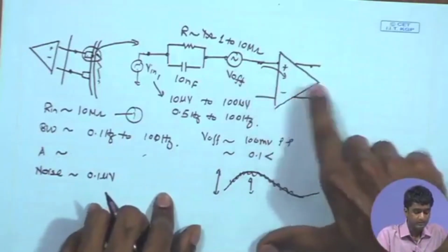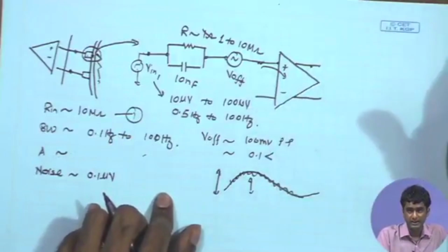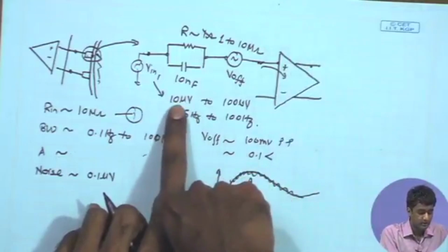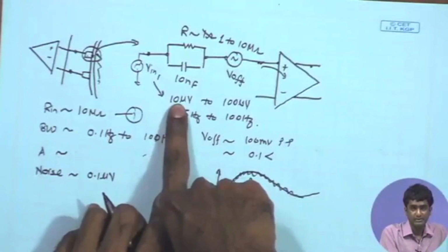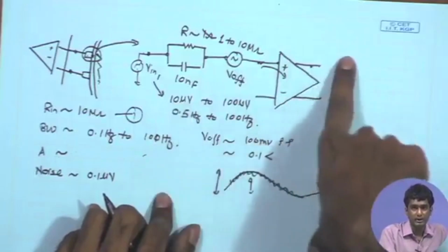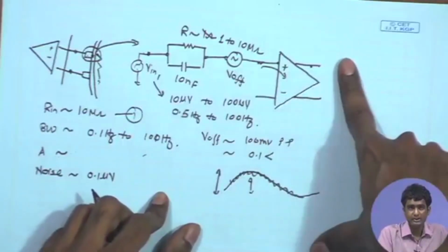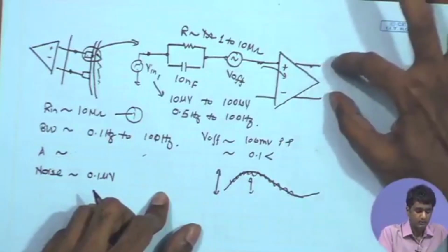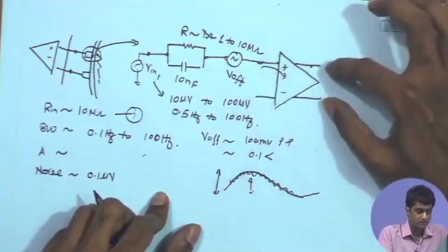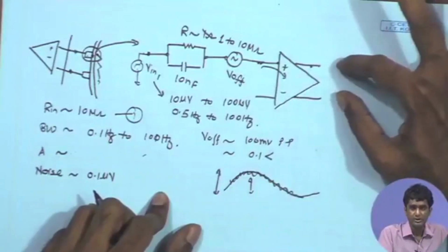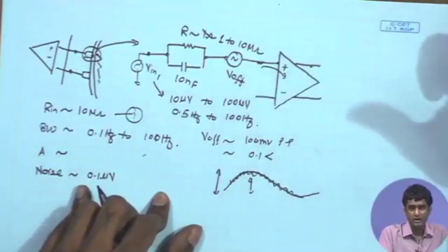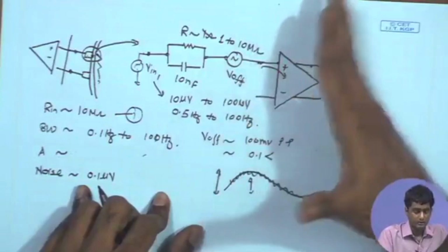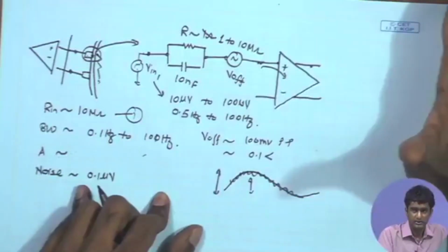So, that means the maximum gain that you can have for the amplifier will be just 10, and even after amplification the desired signal is getting amplified only by a factor of 10. So, from 10 microvolt it will be able to get to 100 microvolt, which is again not at all enough for further processing. And then one of the crudest ways that you can handle this problem is that after this amplification you can try to apply a strong high pass filter, so that it suppresses this slowly varying signal, and then you amplify the rest of the signal, which is the desired signal.